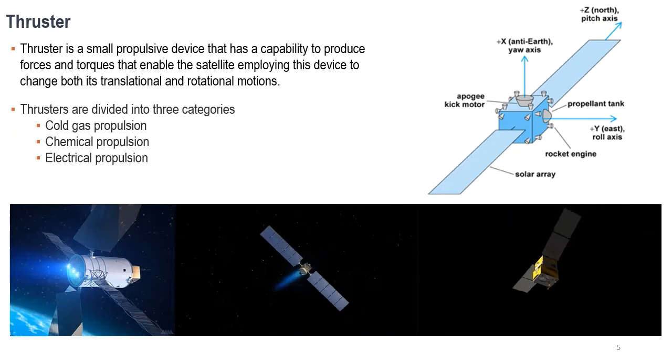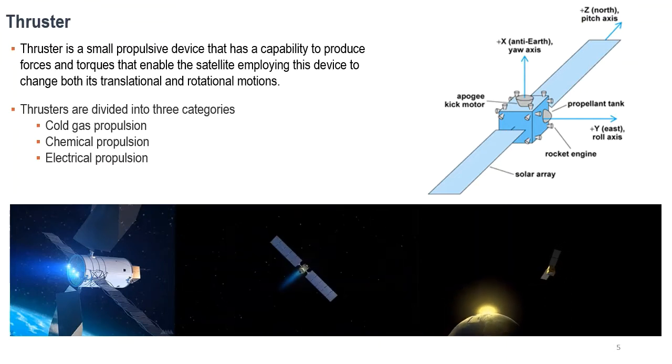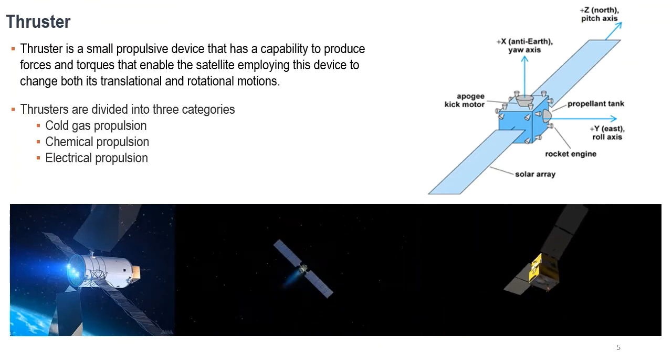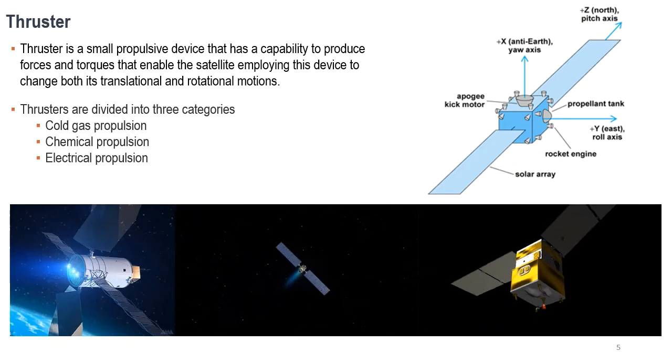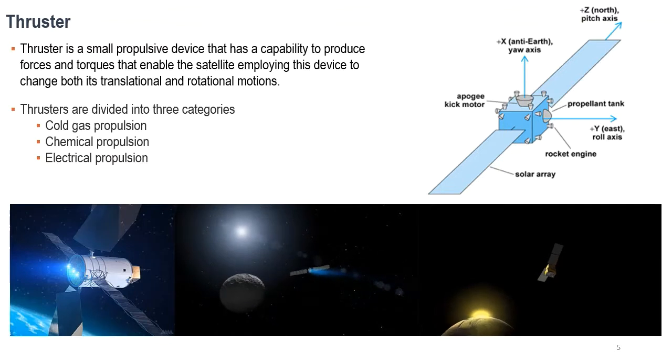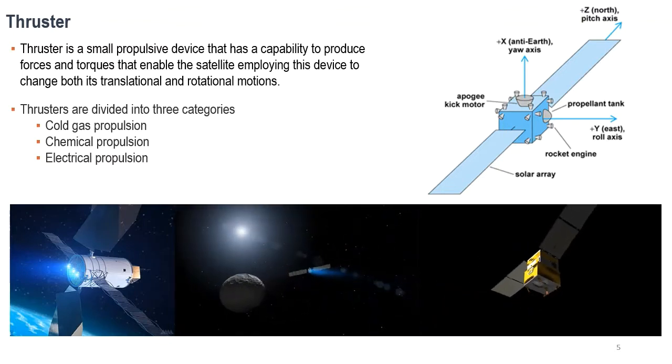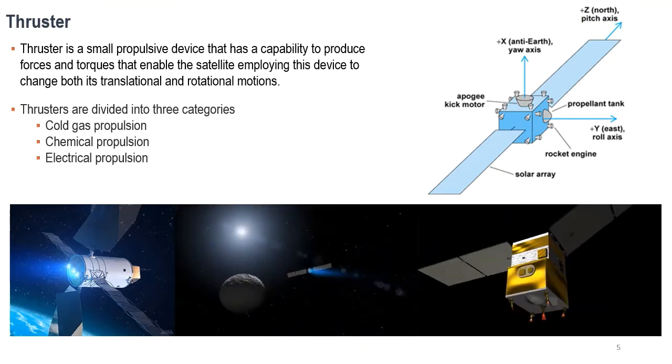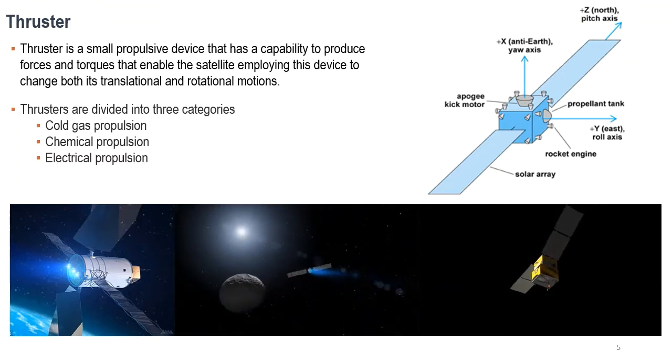Overall, a thruster is able to provide any level of demanded torque, and this capability makes this device suitable for attitude control, nutation control, spin rate control, momentum unloading, and orbit control purposes. However, satellite lifetime is highly dependent on the quantity of fuel carried on board the satellite. The thruster must be operated on-off, and proportional control usually is not feasible. It also requires redundancy, which makes the system more complex and expensive. However, it is fast and powerful, so it is standard equipment on main spacecraft such as the Space Shuttle and re-entry capsules.